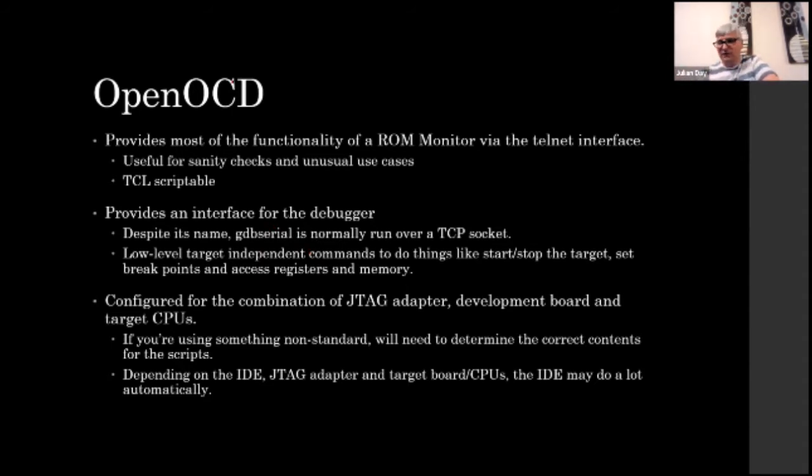And OpenOCD itself is going to need some configuration. You're going to need to tell it how to connect to the JTAG interface you're using, potentially what type of JTAG interface it is, potentially even how the pins are assigned on your interface. Sometimes voltage levels, or JTAG, but not necessarily the JTAG protocol. There are alternatives like cJTAG and single wire debug, which a lot of the adapters support. If you're lucky, your IDE will have some information about it or will set it up automatically based on existing boards.